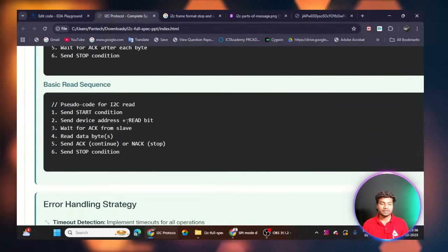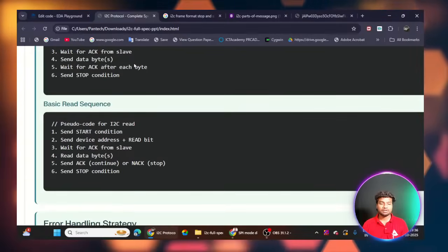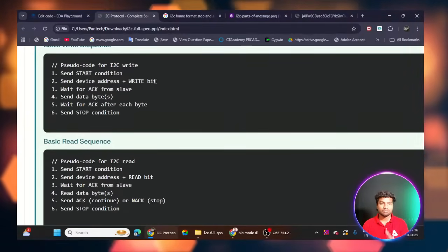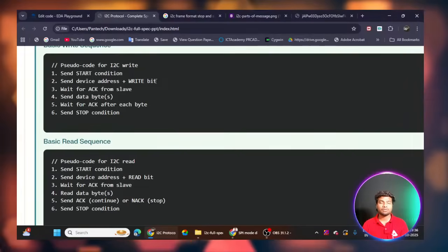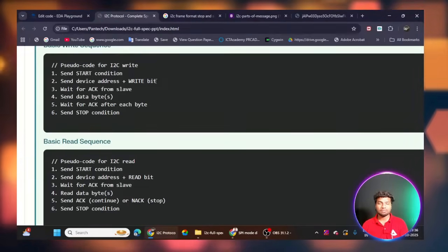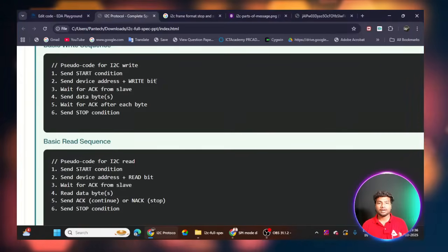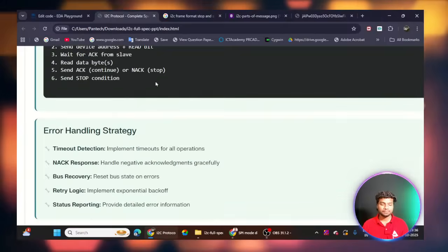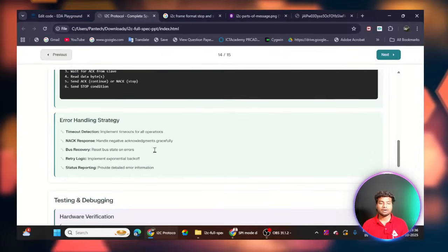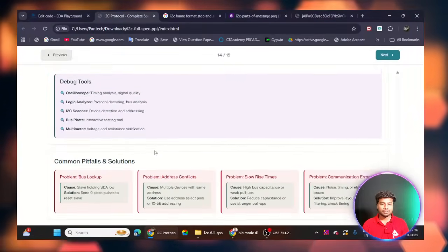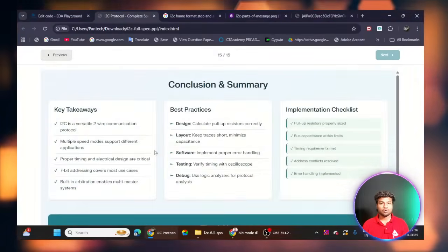So and then there is the read bit. Here I am using the write bit, but it's the same; this is only one bit. If that bit is 0, you can read from the slave. If the read/write bit is 1, you can write into the slave. Okay, this is how we can make the communication between them. And we will see the code in tomorrow's session.